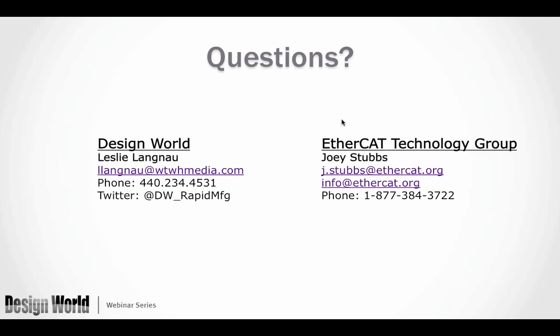Okay. And someone has asked whether or not you can use Wireshark to capture the EtherCAT packets? Certainly can. The parser for EtherCAT has been in Wireshark now for 4 or 5 years, and it is actually a dynamite tool. It's free, and with all of the commands you can interrogate and see everything that's going on in EtherCAT with Wireshark. So it's really the only sniffer tool you need. You don't need a high-cost analyzer or any other similar tool with EtherCAT.